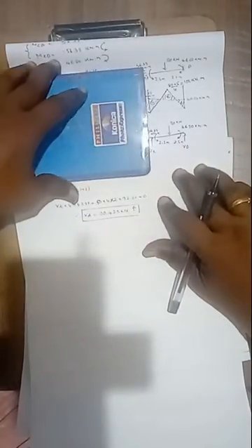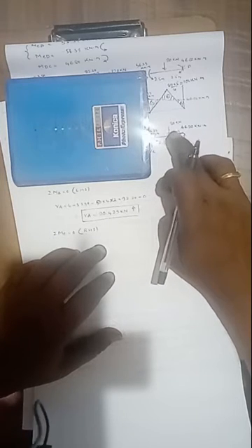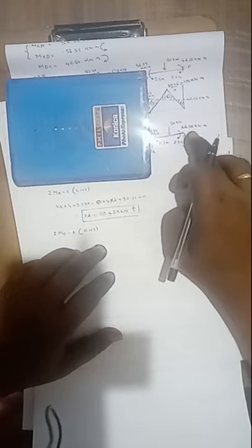Similarly, in the same way we can close the portion CD, that is summation of MC equals 0. Only we have to consider the right hand side of C, which is subjected to an 80 kilonewton point load at the center, and the two support moments, 56.39 and 46.80 kilonewton meter.